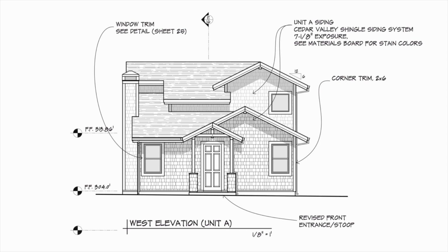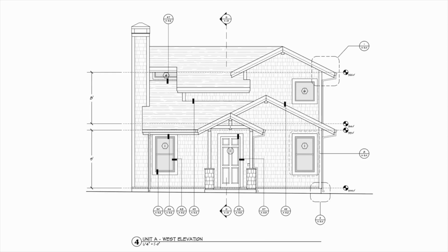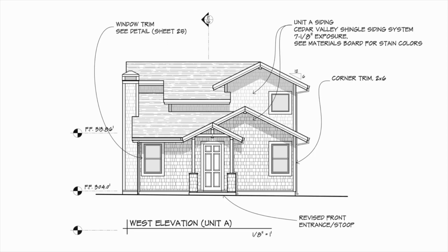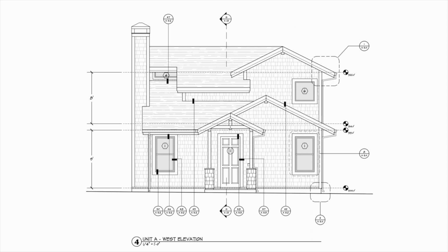When we get to the construction drawing, which is the next one, so all these are the same building, same elevation, this is a technical drawing. This is about how do we build this particular building. Notice that the line weights are still kind of there, but they're really underemphasized now. It's not about that anymore. It's about all the details. It's about all the little dashed lines, the hidden lines, the section lines, the detail marks. That's what I'm trying to read in this drawing. So there's a purpose for each one of these elevations, and my drawings are responding to that purpose. So I'm spending more time with the line weights on this than I am with the line weights on that.